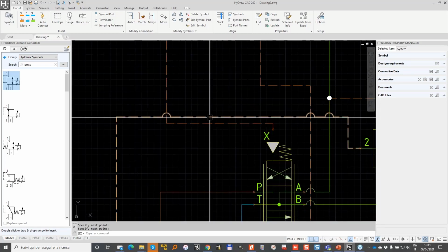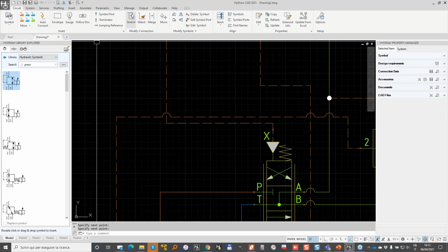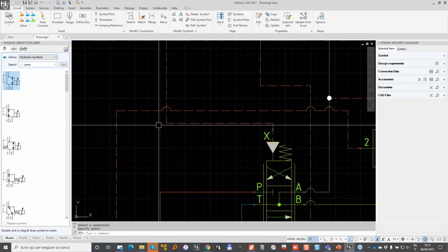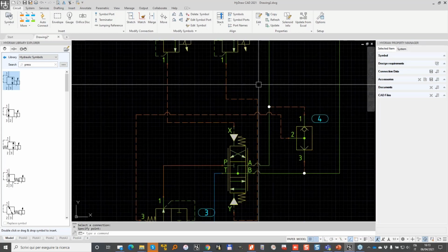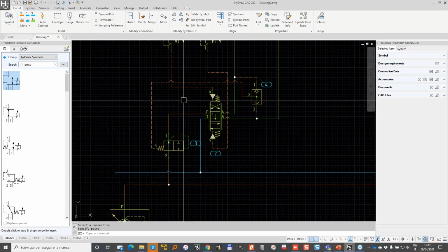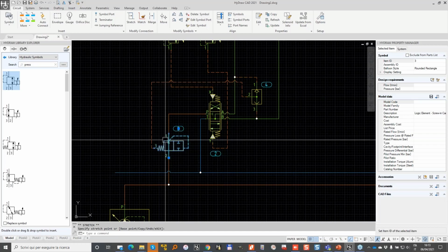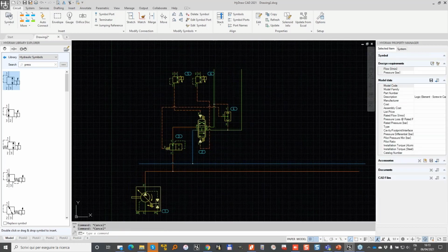Also, in this case, I don't want to have two connection lines too close to each other. Normally, my distance is 4 mm, two modules, two grid units, and so in this case, the diagram looks good. I also want to move this item ID here, and if you want, you can move elements here.